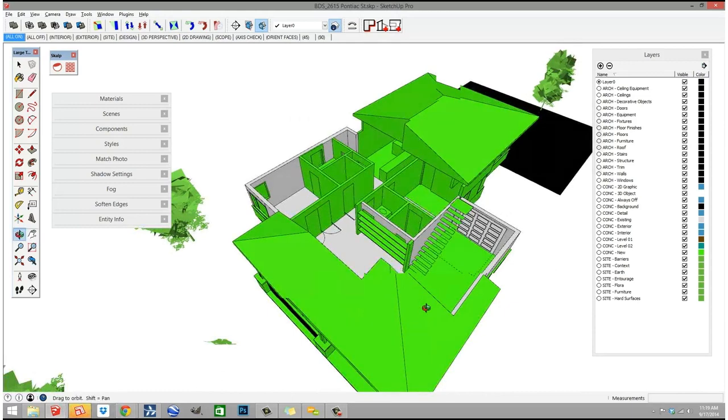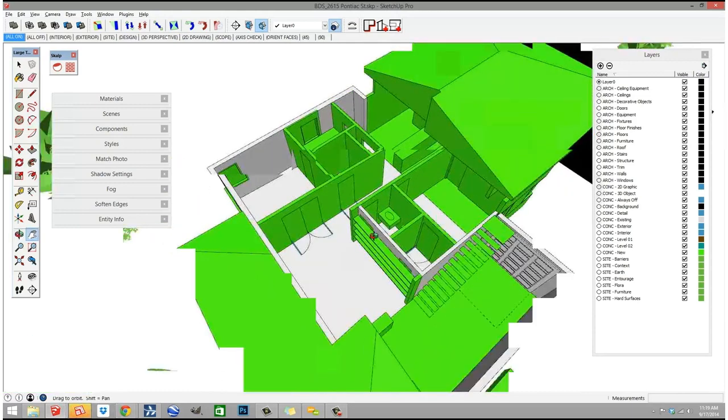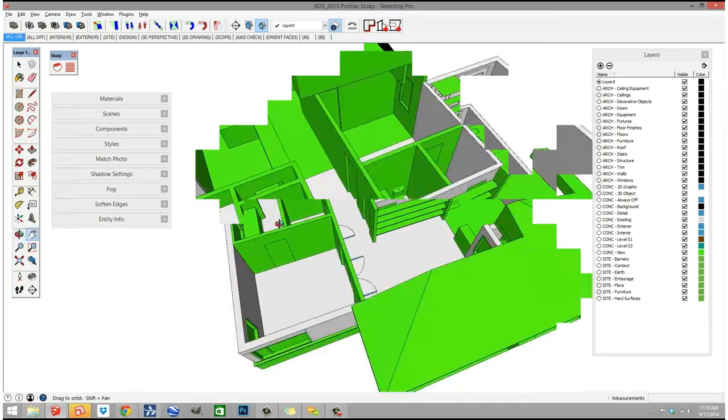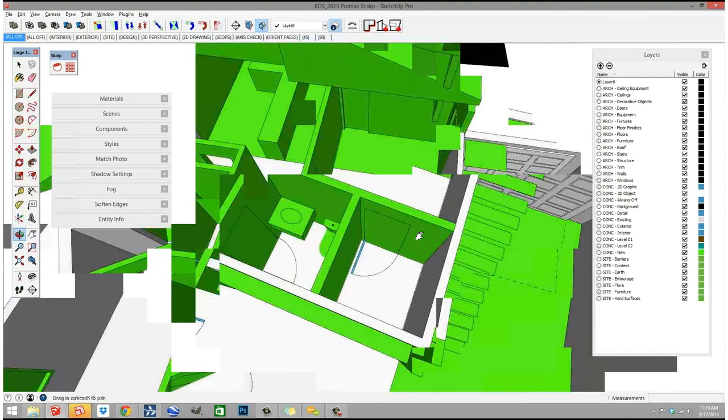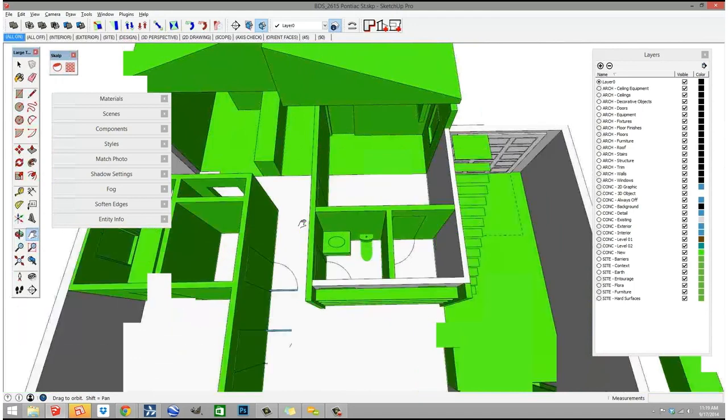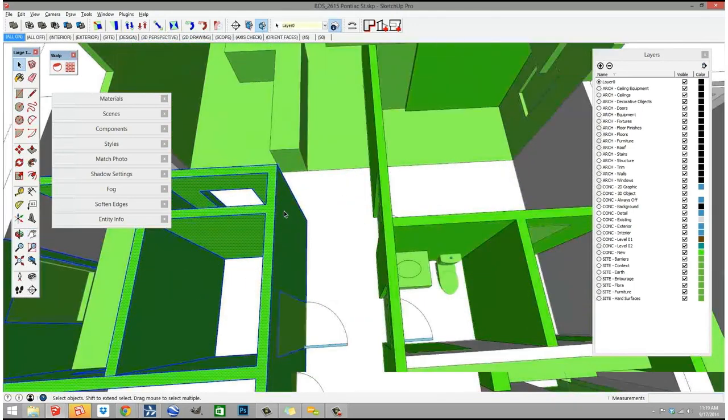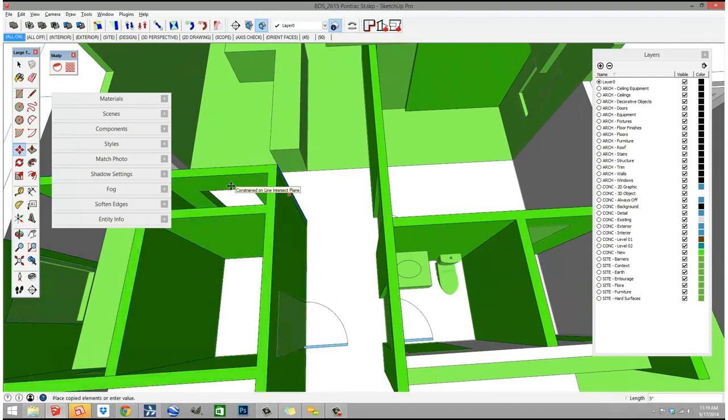So I use this all the time when I'm designing, because if I wanted to add a new wall, let's say I just want to put a wall across here, well, I can just start double clicking into my new walls. And this way I don't always have to be hung up on which layer I'm drafting on, because once everything is layered for me, I can just make sure that I put things in the correct container.